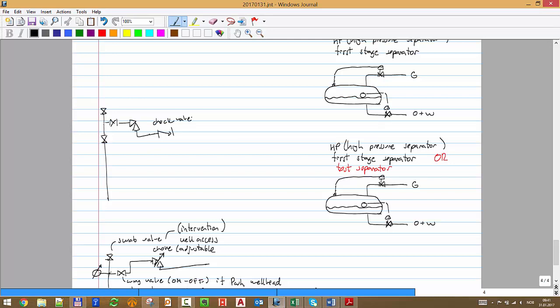In a very simplified scheme, if the fluid goes in this direction, the ball is always open, pressed through the seat. But if the flow tries to go in the opposite direction, the ball is going to close. So that's a one-direction valve, called a check valve.